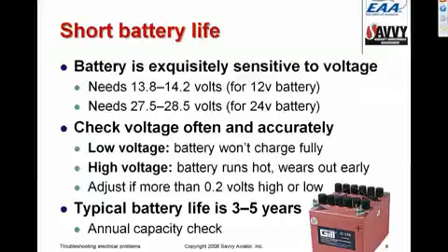So check your voltage often and accurately, and if it gets more than a couple of tenths of a volt off of spec, get it adjusted. That's probably the most common reason that batteries wear out early, is because the bus voltage is too high.